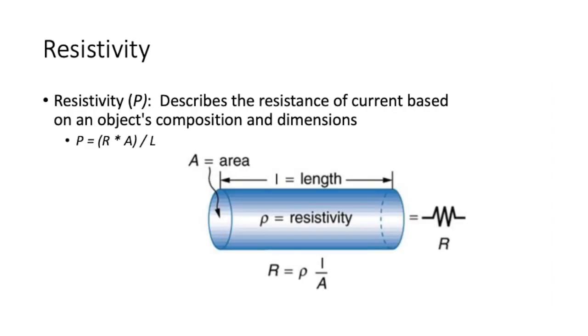While resistance specifically refers to the opposition of charge flow, resistivity is based on the resistor's composition and its dimensions, and how that relates to the resistance of a resistor. Rho, or resistivity, equals the resistance multiplied by the cross-sectional area and divided by the length of a resistor. Longer and larger resistors will offer less resistance, and resistivity values are specific to each material.